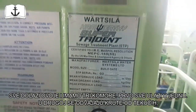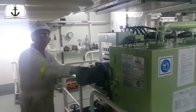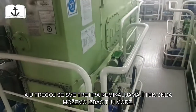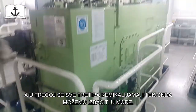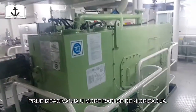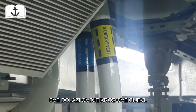So everything is going to these holes, and it has 3 chambers. The first chamber is collecting. The other one is aerated by these compressors, and the bacteria are growing. And in the last one, we're doing the chemical treatment. So you're using hypochlorite, and hypochlorite is injected into the mixture, and then we can legally, in the proper way, discharge into the sea. Before we discharge into the sea, we're using dechlorination. Yeah. So, it all comes from that pipe over there, right? 3 pipes. Black water. Yes. Because it requires sanitary, black water, okay.